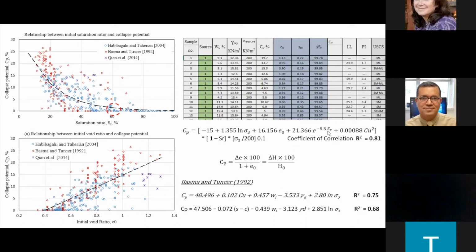Here I'm using the degree of saturation. There they have the conformity coefficient. They are using the vertical effective stress. I'm using the void ratio. And here it is a kind of mix of gamma D and the water content. So try to be very direct when you are dealing with the important and significant properties. You will see that this behavior is mainly controlled or governed by the void ratio, the initial void ratio, the effective stress and the initial degree of saturation.